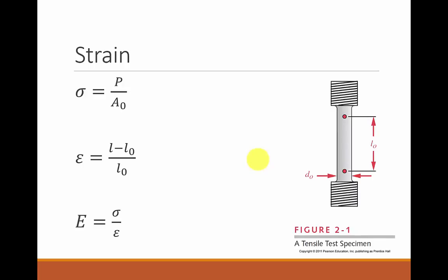The first thing I realize is there's a relationship between stress and the amount of force that's put on a part. So in a very basic tensile test specimen, you take a part that has some sort of diameter, you screw it into your testing machine, you begin to apply a force to pull this part apart. And as we do that, we calculate that the cross-sectional area of this part greatly influences the amount of stress that the part sees. In other words, if this is a part with a very large area, the stress will not be too great, but if it's a very small area with the same force, you'll have a lot more stress induced within the part. And so a very basic understanding, and this is almost just a unit balance, is to recognize that force divided by area is equal to stress.